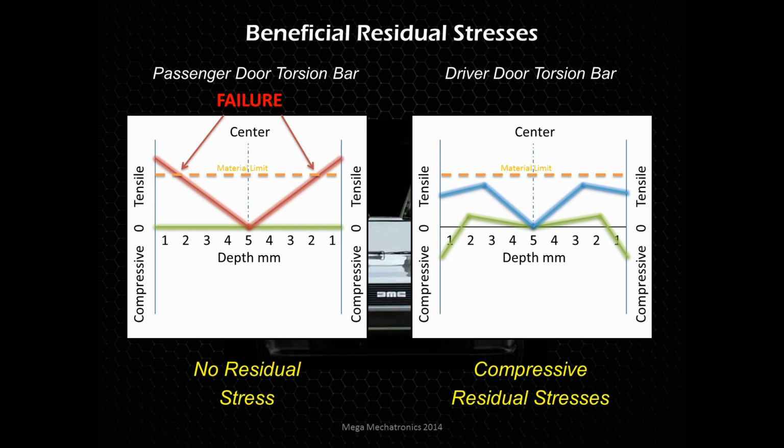So this concept here is what makes valve springs so durable and makes them last so long. Crankshafts and any parts that are cyclically loaded. Aircraft, this is a very big deal. These compressive residual stresses within airplane parts. Very important. So again, the max stress is below the limit.